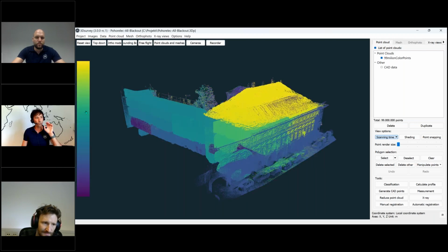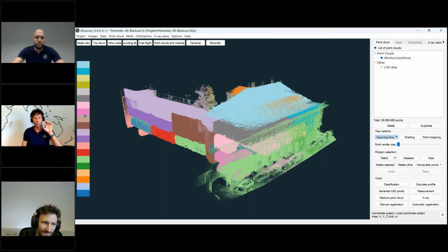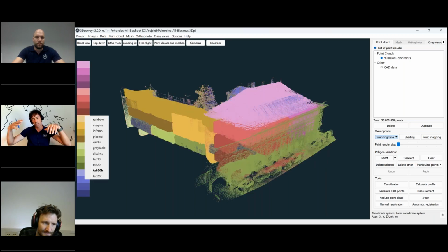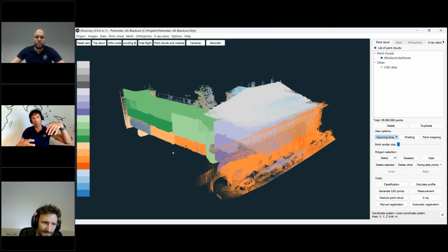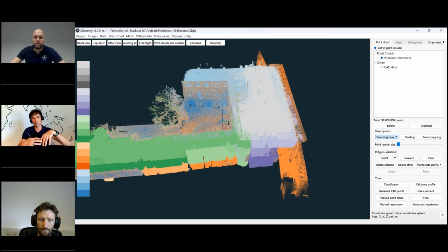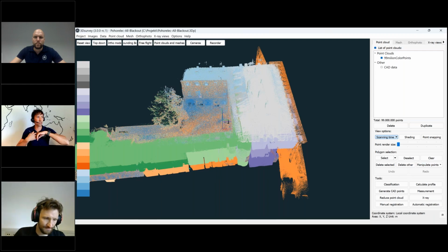It's also if you have, let's say, photogrammetry data and in addition videogrammetry data, and you would like to put those data together. So you can merge, I don't know, mesh with point clouds. You can use the manual registration for point clouds or texture 3D models with models which architects give you, the OBJ file or something like that. So it's quite a bright feature experience.